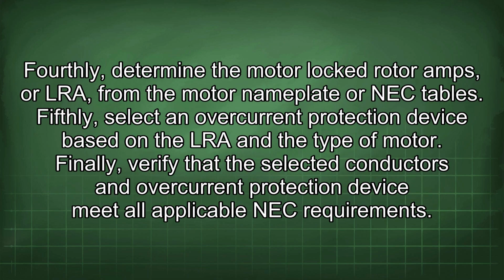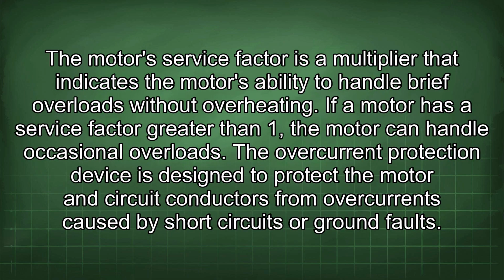Fourthly, determine the motor locked rotor amps, or LRA, from the motor nameplate or NEC tables. Fifthly, select an overcurrent protection device based on the LRA and the type of motor. Finally, verify that the selected conductors and overcurrent protection device meet all applicable NEC requirements. The motor's service factor is a multiplier that indicates the motor's ability to handle brief overloads without overheating. If a motor has a service factor greater than 1, the motor can handle occasional overloads.